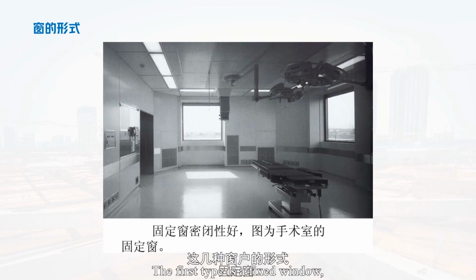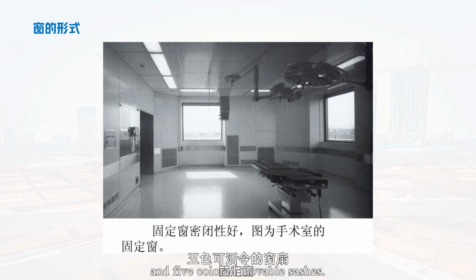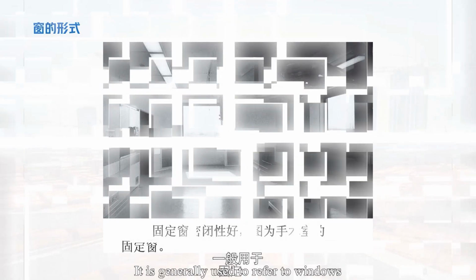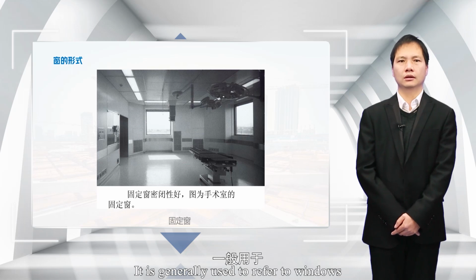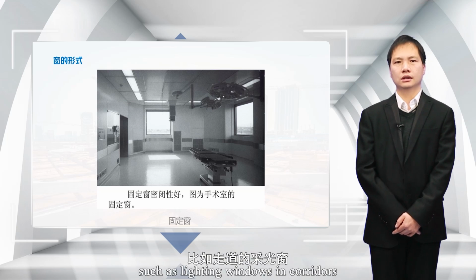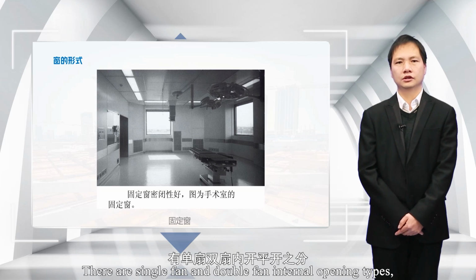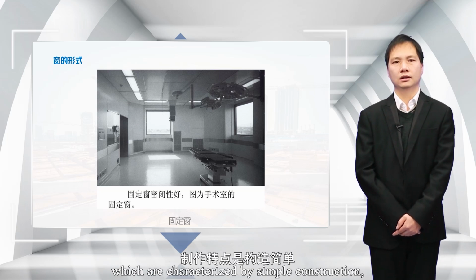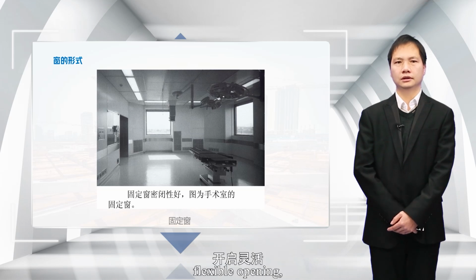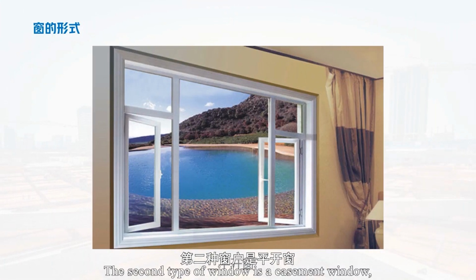The first type is a fixed window, which is a type of window with glass directly embedded in the window frame and no movable sashes. It is generally used for windows that require lighting and observation functions, such as lighting windows in corridors. There are single fan and double fan internal opening types, which are characterized by simple construction, flexible opening, and convenient installation and maintenance. The second type of window is a casement window.